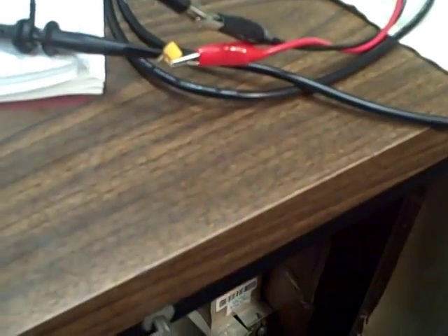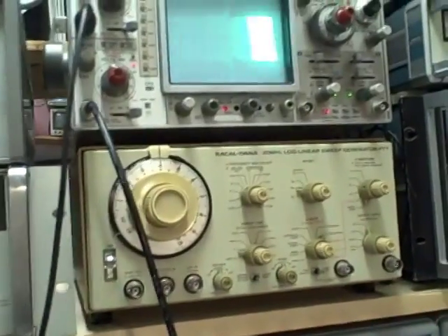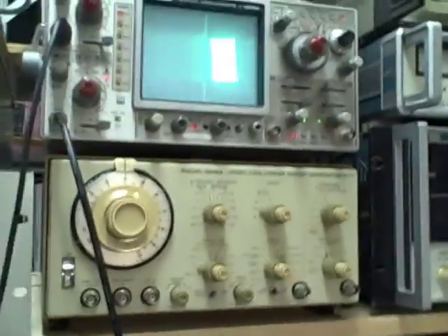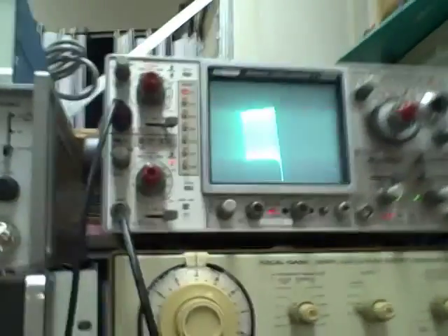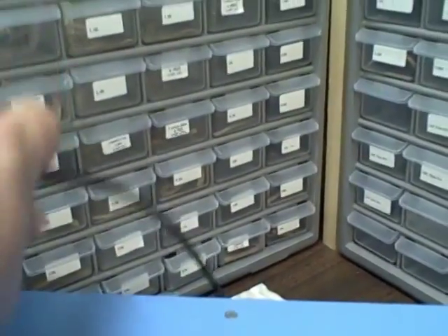Okay, so here what I've done is my little trick with the 455 kilohertz resonator. I've got the ceramic resonator connected in series to the output, and then going into my probe, I have my scope on XY mode. I'm feeding into the B channel the time base sweep, which comes from the rear of the instrument. I have the sweep output.